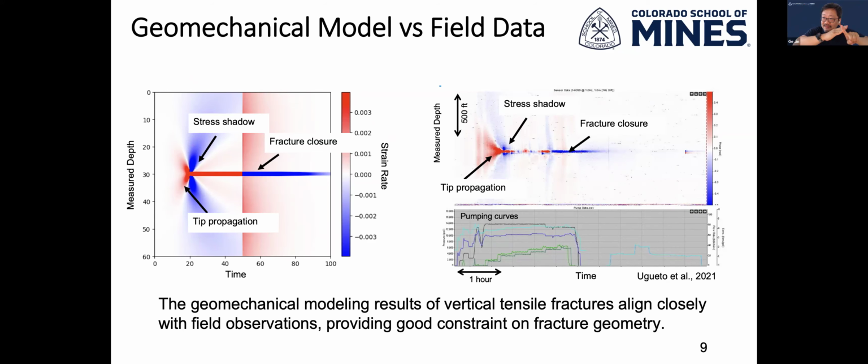So it's actually a response separated by 2 categories. The early stage response is from stage 3 to stage 6. For stage 1 and 2, the response is actually below the end of the fiber, so we don't really have that measurement. But the early stage is one type. And then in the later stages, we find the signal changes very dramatically and very differently. So let me zoom in and tell you how. In the early stage, the fracture still looks like a tensile fracture induced strain signal.